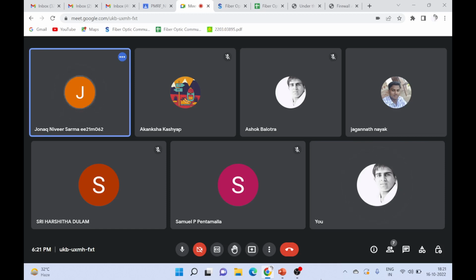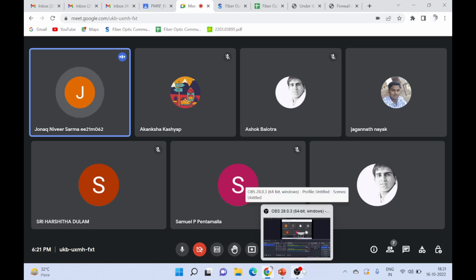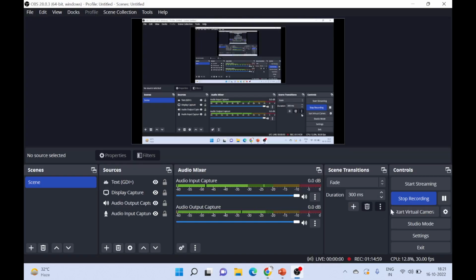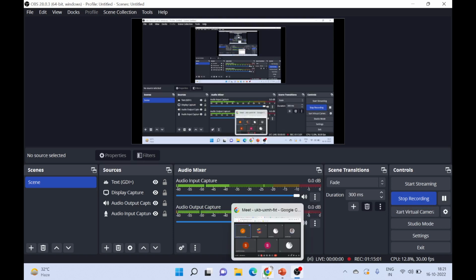You have to find n basically, the number of users. The only thing varying is how many tap couplers there are. You lose 0.5 dB times n in the link, launch 1 milliwatt, lose at each step, and at the last step you only take 5% power, which has to be 100 nanowatt minimum. That's all.